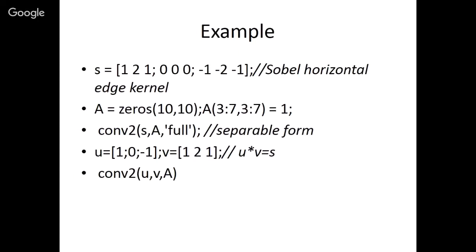So here we have learned how to do single vector convolution with CONV. After that, two-dimensional matrix convolution with CONV2. And if one input is in matrix form and another is in vector form, then we can also use CONV2.